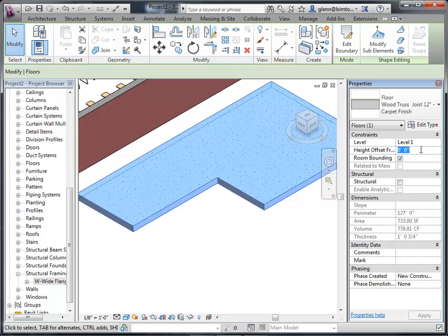Right now it's right at Level 1. Level 1 is typically the height of the subfloor. That'll probably be pretty good if that's inside the building. If this is outside the building, and I was doing this as a concrete patio, I'd probably drop it down a few inches, so that water won't flow into the building. Landings and things like that are typically recessed just a little bit.